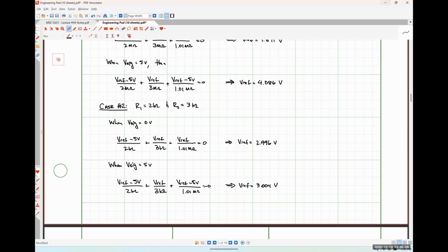Whereas if we use the kilo ohm size resistors, the current's going to be on the order of milliamps. So we can use very cheap, quarter watt or an eighth watt rated resistors that you can get for a nickel, right? So we get a marginally better electrical performance by using really, really low resistors, but the cost of those components is tens to hundreds of times more expensive than if we use kilo ohm size resistors.